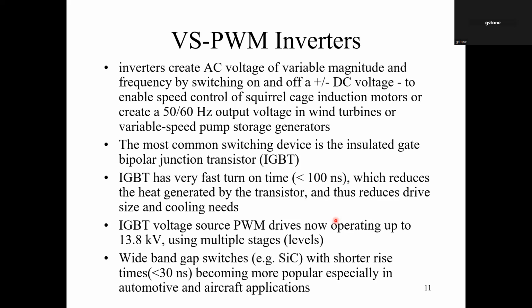In fact, I'm aware of one situation in an electric vehicle application where the rise time of the voltage impulse that can strike that stator winding is as short as 7 nanoseconds. Okay, and there are reasons why they want to make that rise time shorter. The shorter the rise time, the less heat that will be created. Therefore, the more efficient the drive will become.